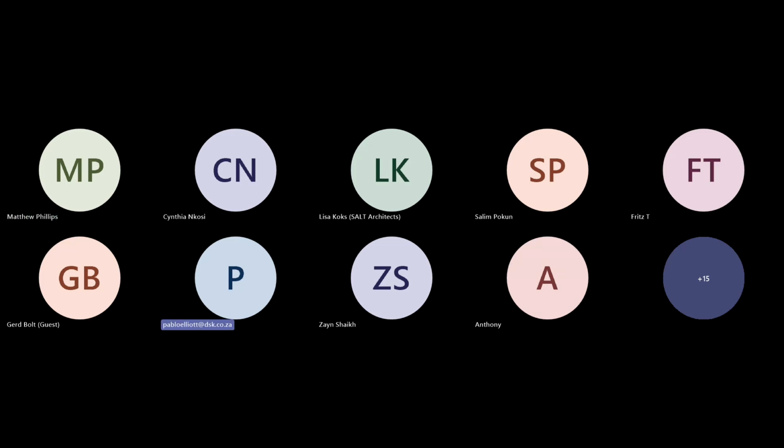Yeah, sure. It's a tricky one. I won't say that we haven't had leaks, but what we did was, well, the CLT needs to breathe, so we put what they call a vapor barrier, which is a breathable fabric manufactured in Austria, on top of the cork directly, and then battens, and then that has the breathing space. I've got a roof light in my double volume space, which is an operable roof window, and around it there is a chimney which allows air to escape. So the roof breathes